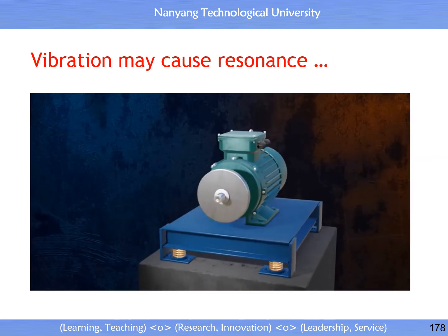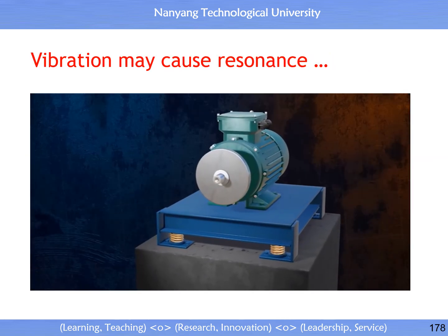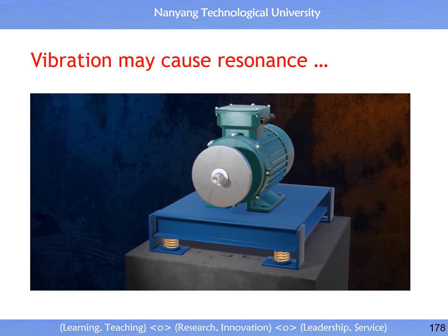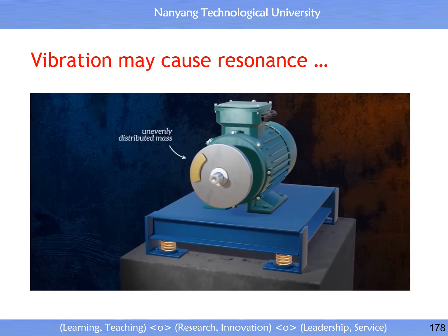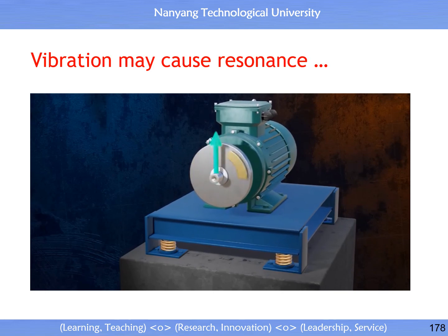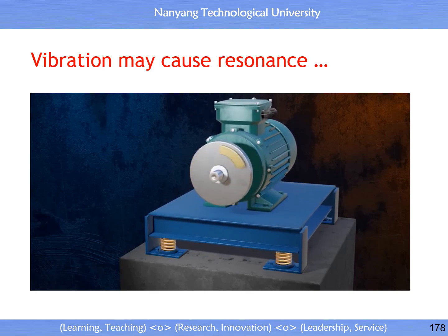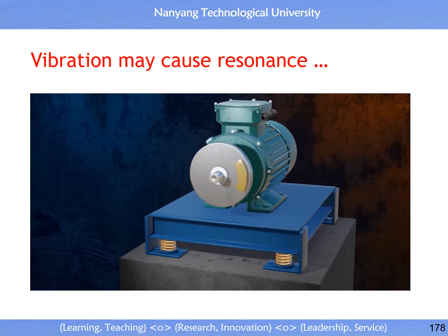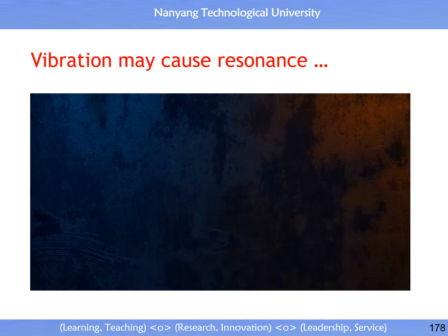With turbines and motors, forced vibration occurs when a rotating component is unbalanced, meaning that its mass is unevenly distributed. This introduces a load that has a sinusoidal component in the vertical direction and can cause vibration. Unbalance can occur because components were poorly fabricated or have been distorted. But eccentric masses are sometimes added to motors on purpose. Intentionally unbalanced motors are how phones and video game controllers are able to vibrate.